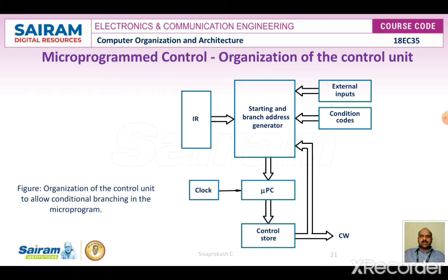After loading the instruction in the IR, a branch instruction transfers control to the corresponding micro routine, which is assumed to start at location 25 in the control store. This address is the corresponding output of the starting address generator block. If this bit is equal to 0, a branch takes place to location 0 to fetch a new machine instruction. Otherwise, the micro instruction at location 27 loads the address into the program counter.